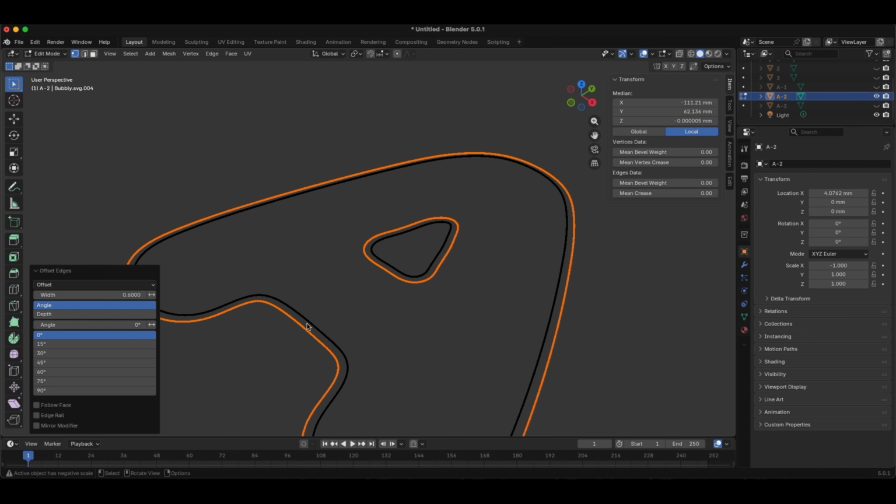This is going to be the support for this blade, because 0.4 is too thin. It is good for cutting, but it's too thin for printing, for holding it. So it needs to be supported by another wall. In total, it will give us 1 millimeter. That is why 0.6, not minus, but plus, yeah?